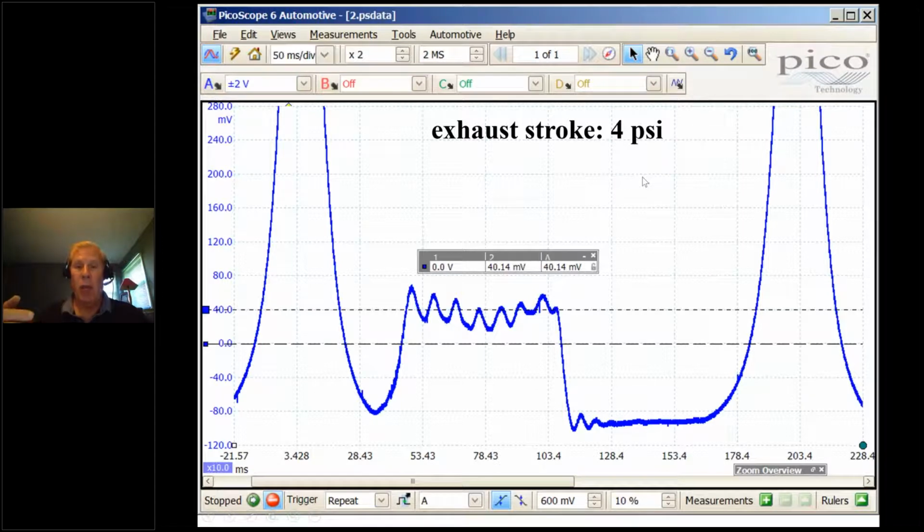So generally, when you have a converter, as an example, that has a restriction, once the valve opens and the pressure rises back, it will go higher than 0. So this would be a clue of a converter as opposed to an advanced exhaust cam or a worn lobe.